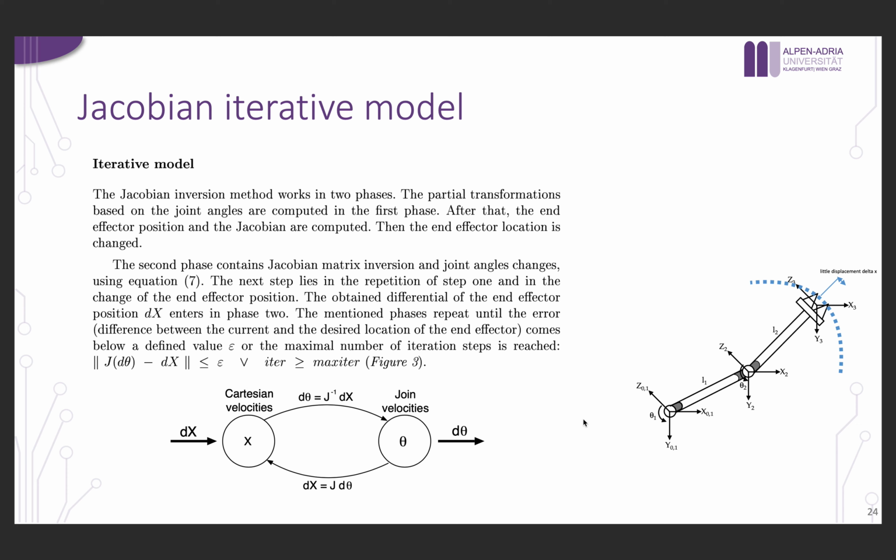So I apply this angular velocity, which would move the robot arm with the hope of reaching the target dx. Okay. Now, if I apply the forward kinematics, so let's say I take this delta theta and multiply it by the Jacobian matrix, not the inverse, I would get an estimated delta x, which is the output of my pseudo estimation.